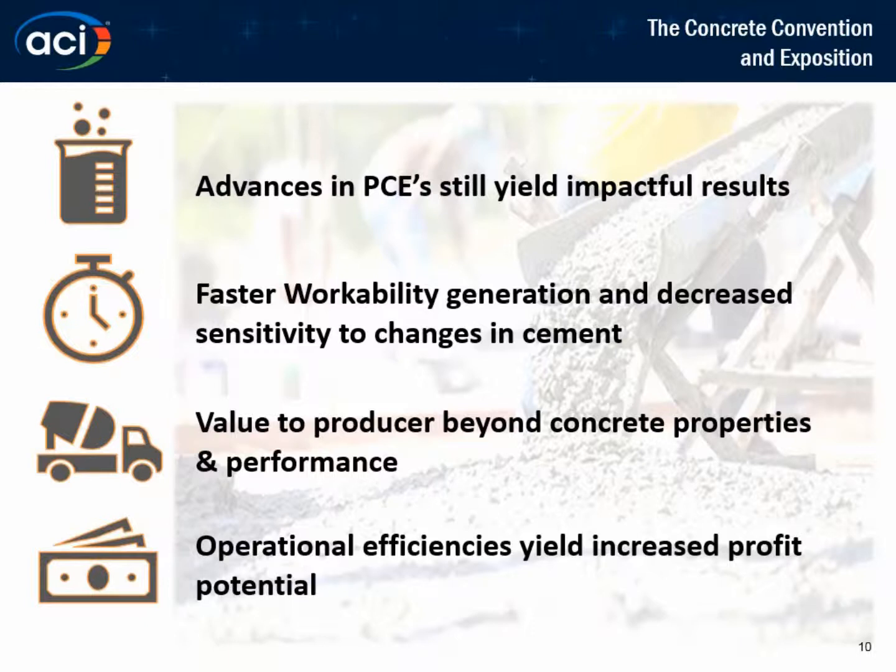So there were many trials that were run, and what we tried to do was replicate the existing process. So if the existing process of a certain ready mix producer was to batch everything into the water and then hit it with the admixture, we did it that way so that the time comparison was identical. In other operations, we had it up front with the mixed water. So they had the water in, they added the admixture, and then the materials. And in both scenarios, directionally, the wet out characteristics were the same in terms of they were faster versus the traditional PCE that they used.